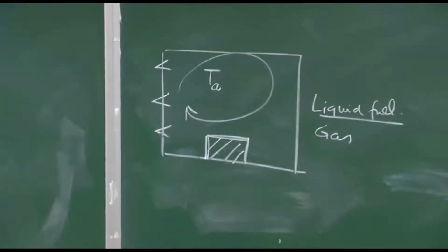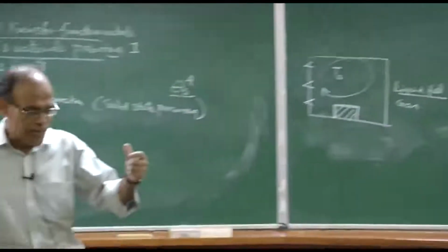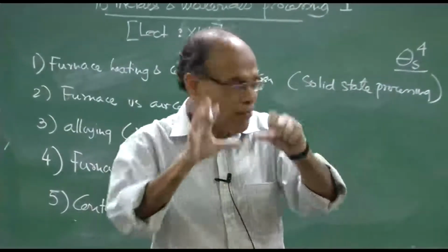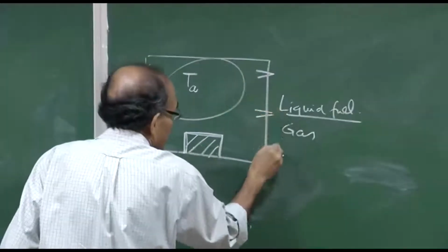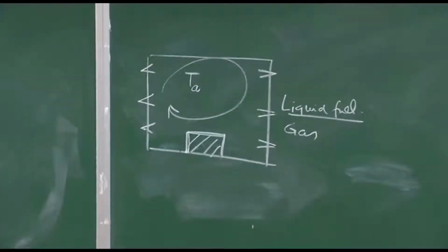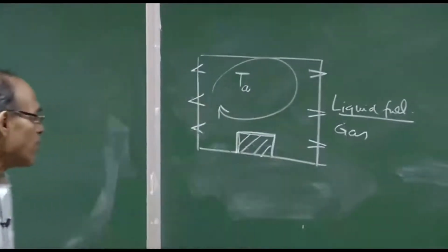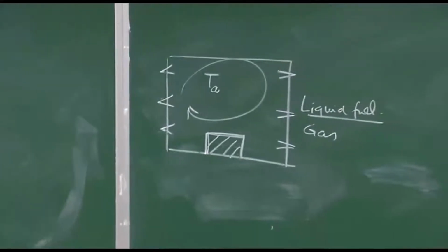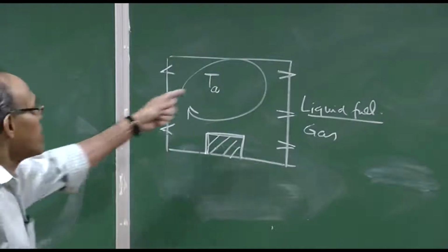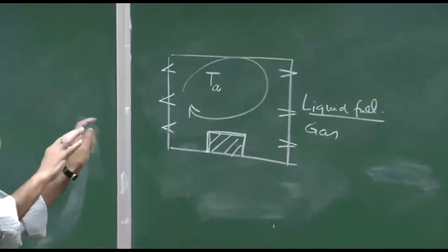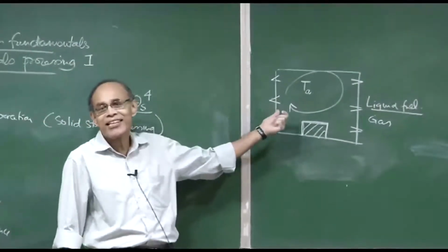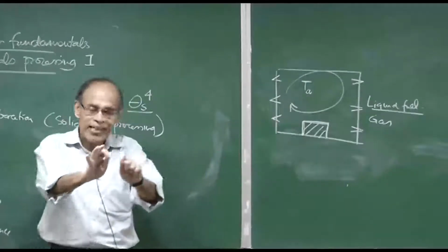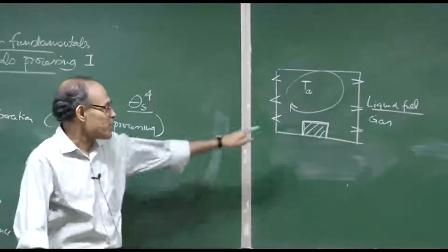Typically what happens is, suppose you start firing the furnace by injecting gaseous fuel or liquid fuel into the furnace. These are my schematically shown burners. Once you start doing that, after some time the furnace attains a constant temperature, the desirable temperature, which may be 1200 degrees centigrade for steel industries, for example. It is at that time you put the solid objects into the furnace.